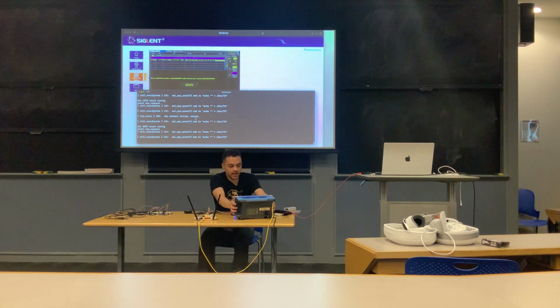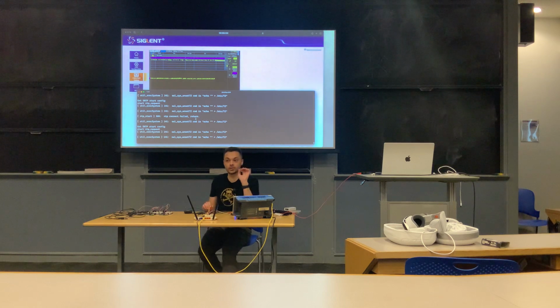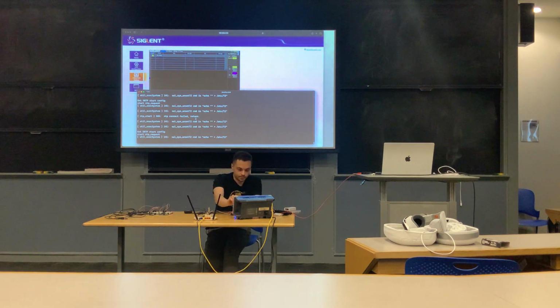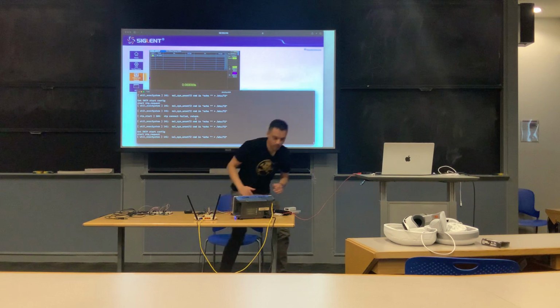And so now what I'm going to do is actually configure the oscilloscope to watch for those UART transactions and stop when it sees one. So this is a thing you can do. Instead of doing edge triggering, we're going to do a serial triggering. And this is just like a known pattern. So we're going to select our protocol as UART. We'll talk about what UART is in just a second. But that's the protocol that's being sent here. We'll configure our TX pin. And we'll go ahead and run it. Zoom out a little bit.